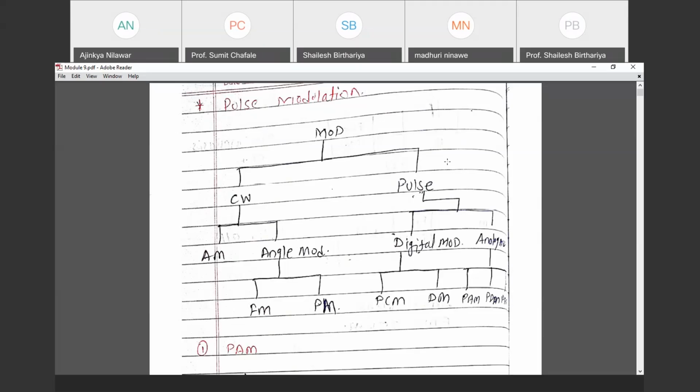Then next is the shift keying techniques. In the shift keying technique, the input is digital, and inside the channel analog data is there, right? We have seen 4 different shift keying techniques. First is ASK, in which if data 0 is there, no carrier signal; if data 1 is there, carrier signal. Then we have seen FSK. There are 2 frequency levels, low and high. If 0 is there, it gets multiplied by the low frequency. If data 1 is there, it gets multiplied by the high frequency.